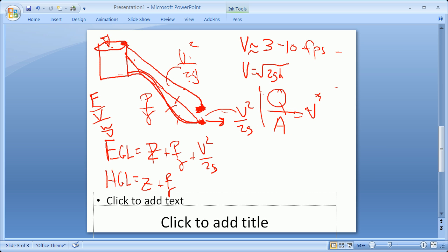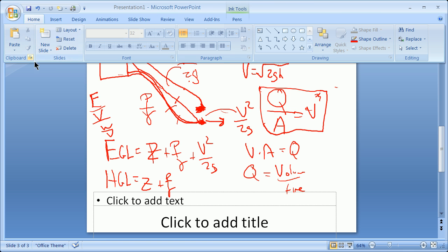You realize that a lot of what we'll do in these discussions through your projects has to do with basically this: velocity times area equals Q, and the definition of Q equals volume over time. But we do want you to understand and be aware of Bernoulli's equation, being this spot that we set you up with, because of how it permeates anything having to do with energy. So to finish out these 15 minutes, I'm going to go to one last slide and then talk about what you pay for if you are pumping a project.